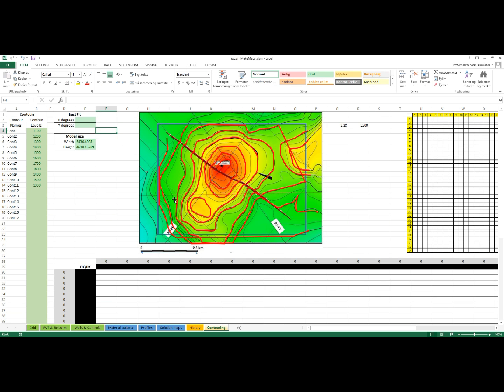Now the surface map is a function, and you can see that I go up the hill here and then down and then up. Up, down, up, down. So it's 3 or 4 degrees. I'll choose 5 degrees in the X direction. And in the Y direction, here you go up and down the saddle, up and down. So I'll say at least 4 degrees. I'll choose 5 degrees.